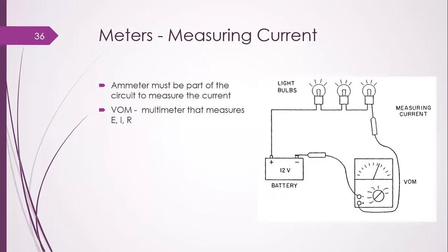So further, this is another way to measure the current. If we need to measure the current of the same circuit, you can see that the circuit is now open, and the two probes are connected in between. How much current is drawn by this series circuit of bulbs can appear as needle deflection on the meter screen. We first need to select the ampere range with the selector switch, and in series notation we connect the meter in series.